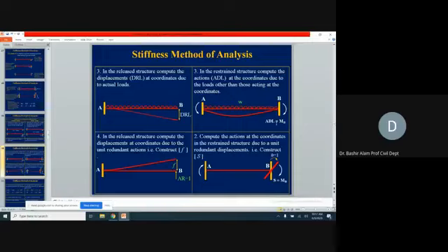So you don't need to do anything special. If you know the equations, you just plug in the W and L values and find out the ADL value. Again, you will have to look at the direction of the movement. If this movement is matching the direction of the D, which you assume is your positive one, then it will be positive. If not matching, it will be negative.